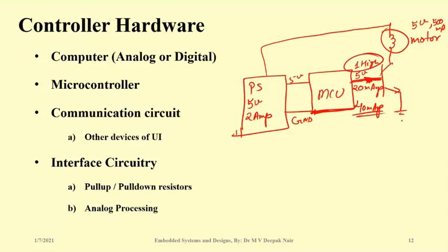Circuit is correct. Because look, at the base, when the base is high, the transistor will act as a short circuit. And all the power that is here, 5 volt and 2 ampere, is here. So we don't have to worry about the current either. It needs only 500 milliampere, so it is enough current. The transistor is acting as a short circuit, so the motor is getting enough power to run.